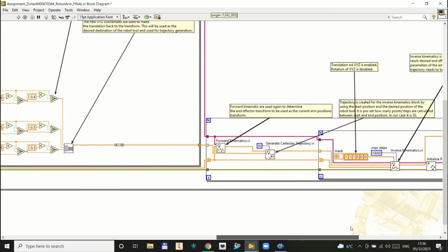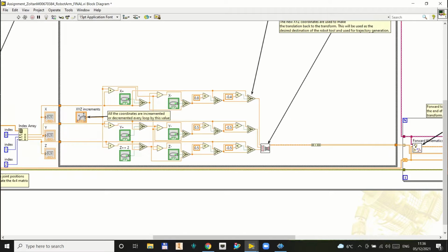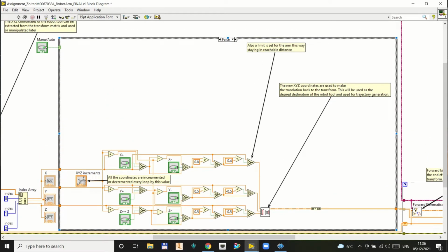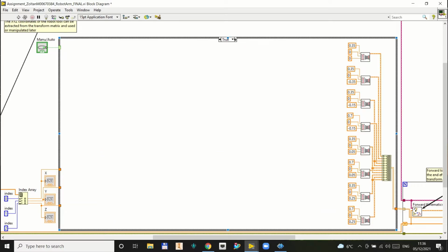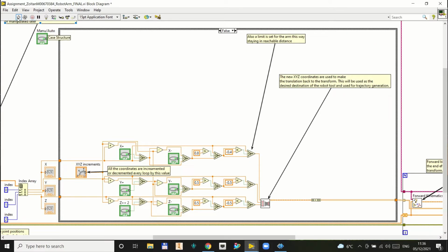After fixing a few missing connections and commenting the code for others to understand more easily, the robot parameters can be tested in the environment to determine if it is fit for the task. This is a good way of planning a robot arm before a time-consuming and expensive building procedure, as it points out errors in the early planning stage.